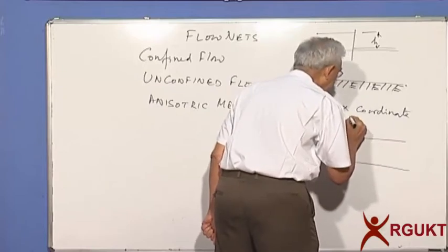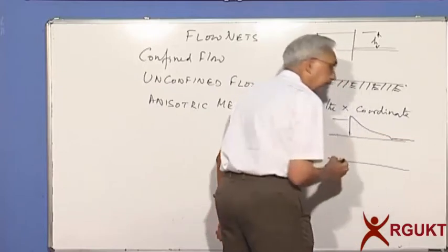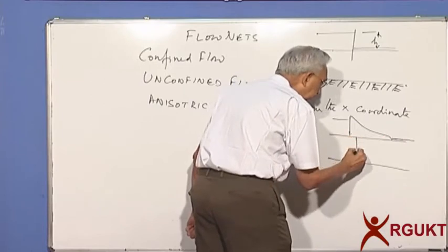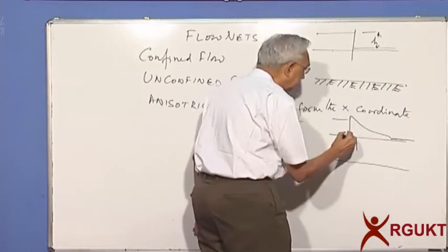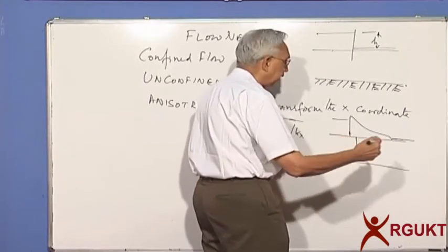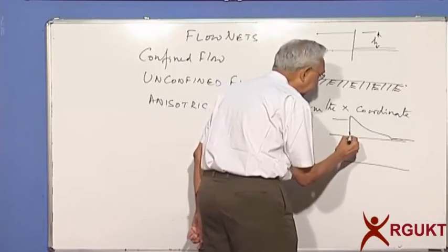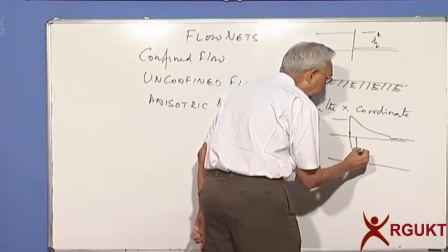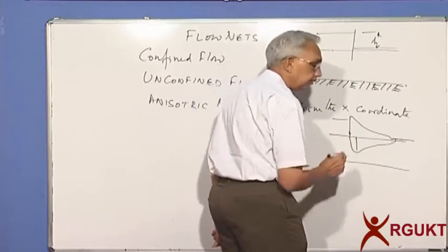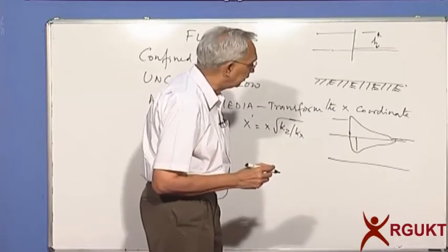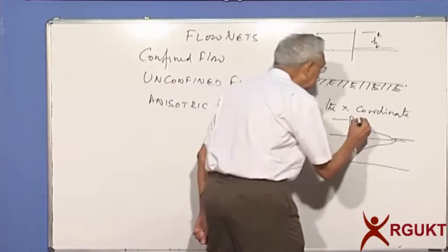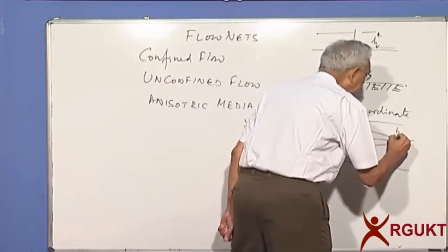Let's say I'm having a weir here. We can also provide a sheet pile or a cutoff so that the length of the flow path increases, which means the flow will now be longer than what it would have been if there had been no sheet pile. So here again is the net head difference H.